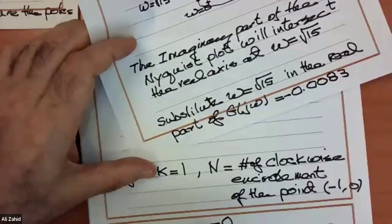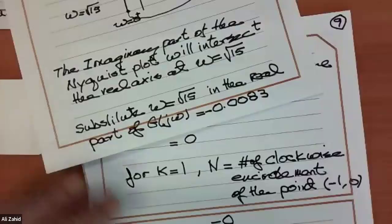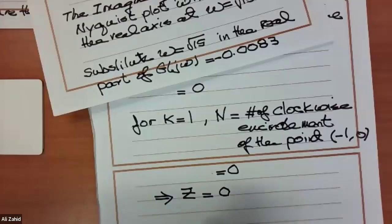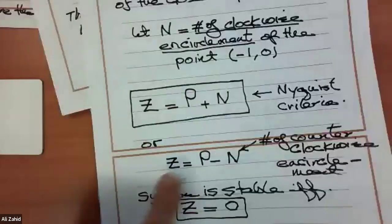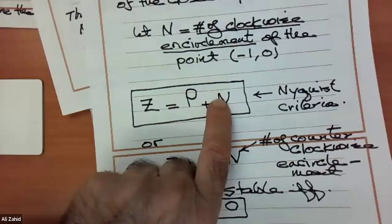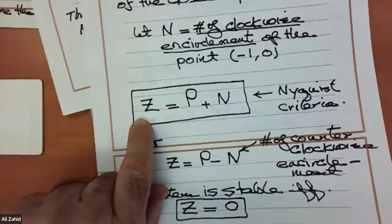What does that mean? It means that the closed loop transfer function is stable. Remember, Z equals P plus what? N. And remember, N is the number of clockwise encirclements. So N is equal to 0, P equal to 0. What is Z? 0.